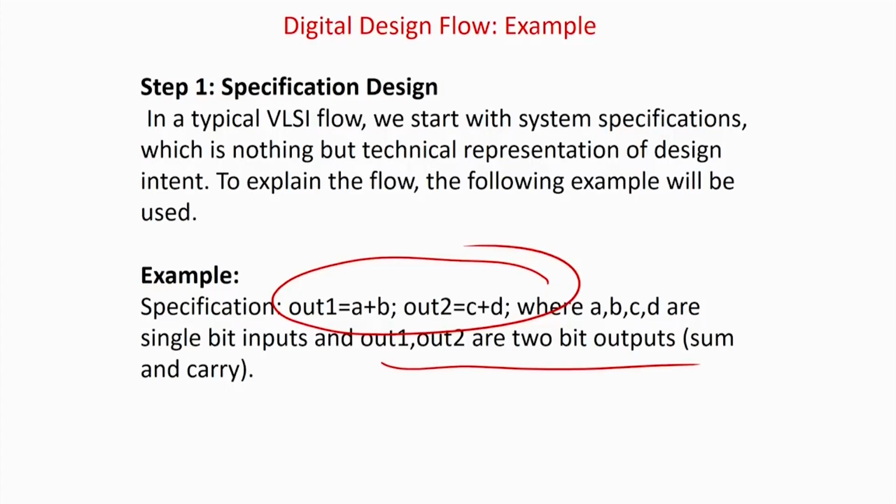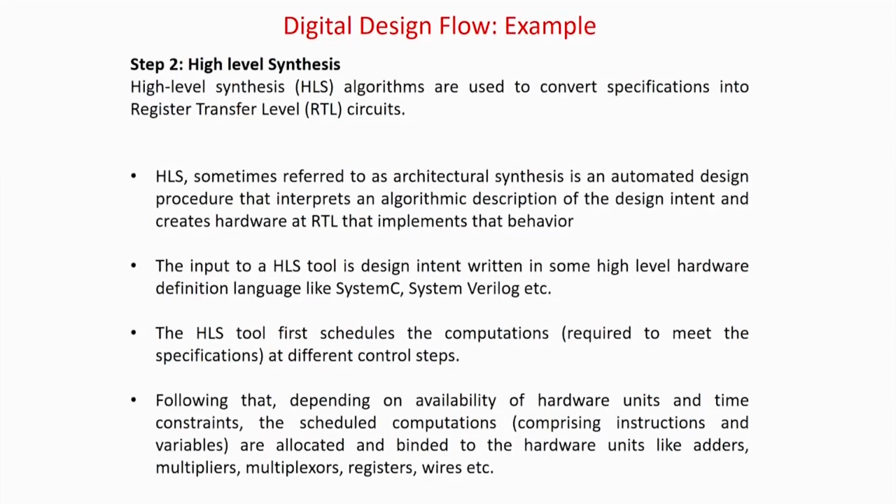Then you have to think where you have to put adders, what multipliers you will require, what the broad circuit diagram will be, etc. But in this case it is a very simple specification, so you can just think an adder is required. Maybe you can also say a simple half adder will do, because there is no carry business here.